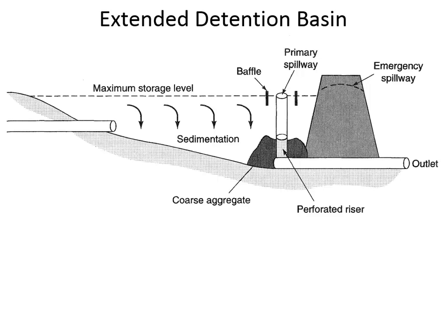So here's a cross-sectional view of an extended detention basin. Now this is the one that doesn't have water in it all of the time. And if you look at some of the features that are here from a hydraulic basis, what you have is an outlet that is essentially governed by the orifice equation. There's going to be some water level, and we know that the orifice equation is that velocity is the square root of 2gh.